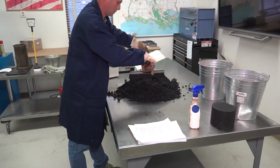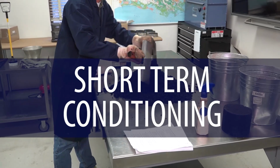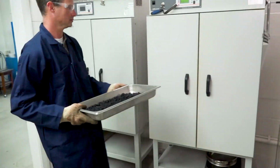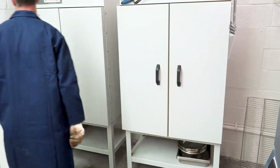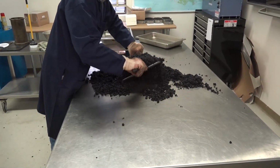A key and vital step in testing for GMM is to prepare the sample for short-term conditioning. Short-term conditioning at the specified temperature is especially important when absorptive aggregate are used. This short-term conditioning will ensure the calculations of realistic values for the amount of asphalt absorbed by the aggregate and void properties of the mix.